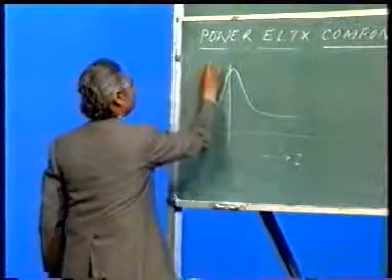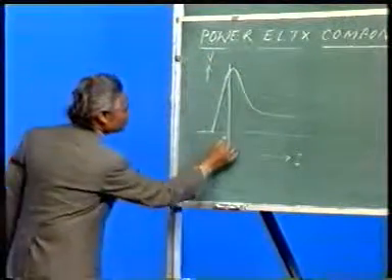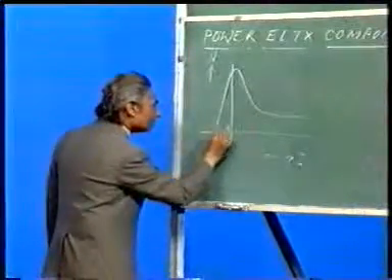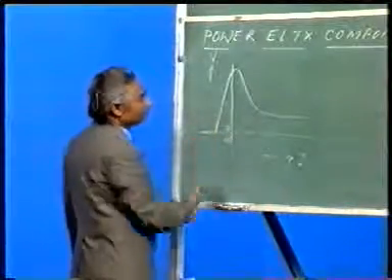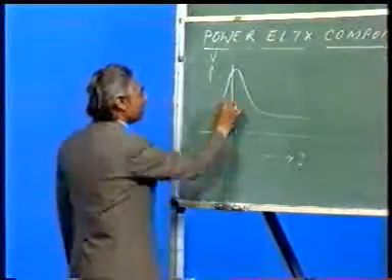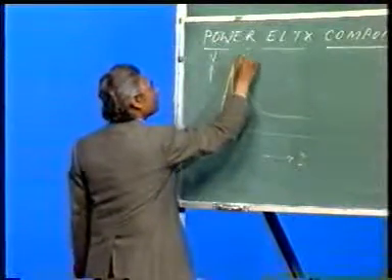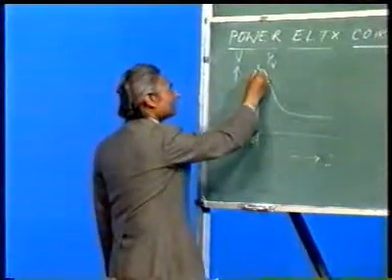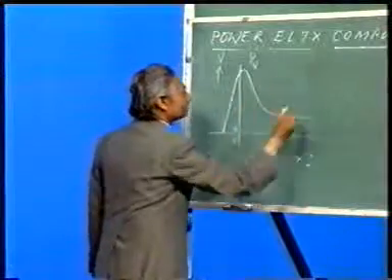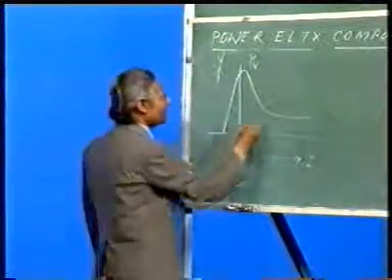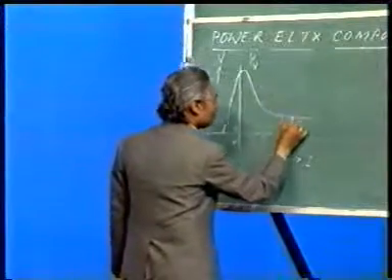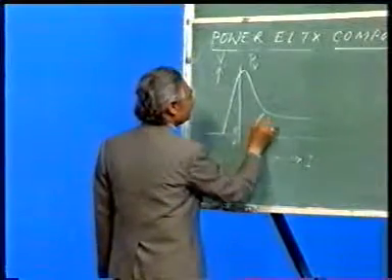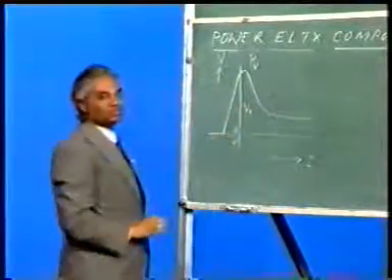and this is voltage. So you find that this point is 0, so this is minus current, negative current. That means this is known as the cutoff region. Here the device does not conduct at all, the current is negative. And at this point, which is known as peak point, and the voltage corresponding to this is known as peak point voltage, the device starts conducting, but it has a negative resistance characteristic, drooping characteristic. And here you find that it is decreasing, but here the voltage remains almost constant, and this particular voltage is known as valley voltage.